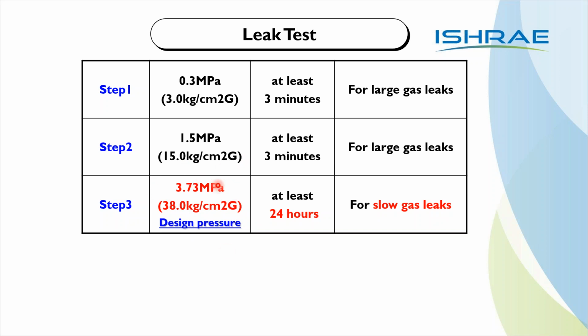Minimum pressure 450 psi to 550 psi, again based on the manufacturer. Again, minimum 24 hours. I would rather say do it for 48 hours and not 24 hours. So the pressure will change approximately. Now, this is again very, very important: you need to note down the time and the ambient temperature.